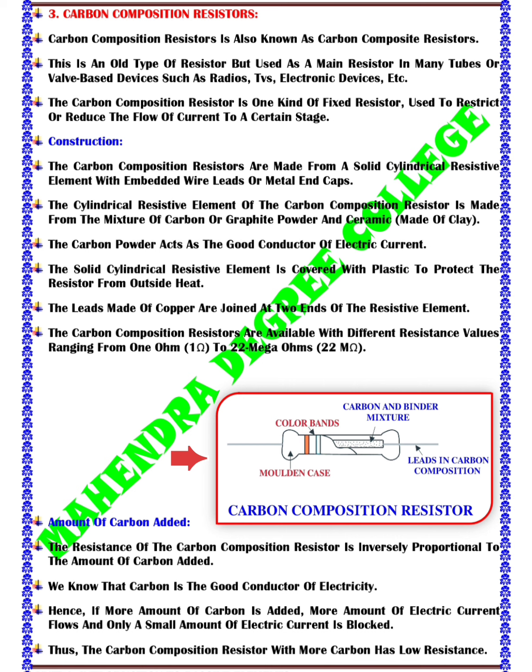The process of manufacturing a carbon composition resistor is as follows. The raw material is a blend of graphite, ceramic dust, and resin. The mixture of these materials is pressed under high temperature and pressure to form it into sticks. Two metal caps are fitted at both ends of the stick-shaped resistor. The assembly is then heated up, and after this process of baking, a massive resistance body is created.